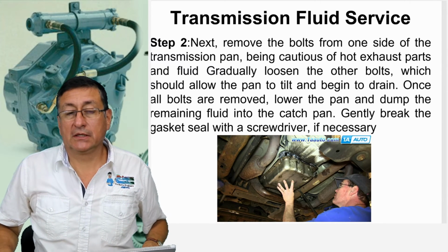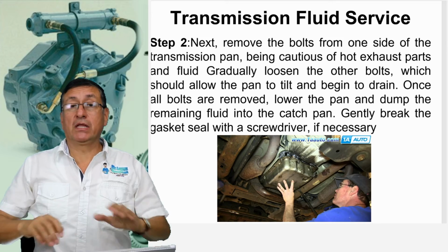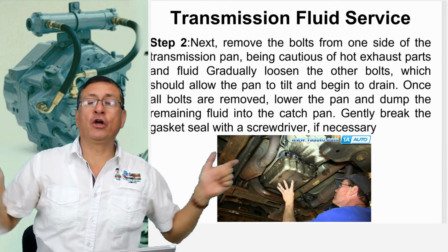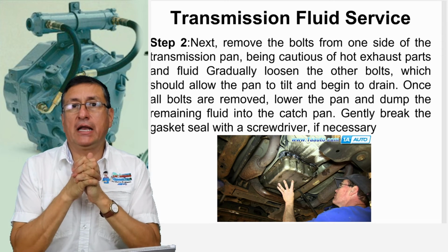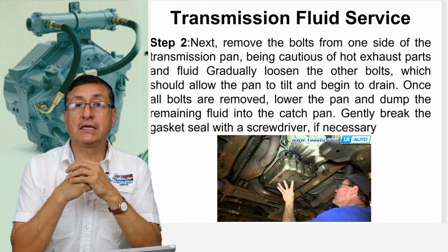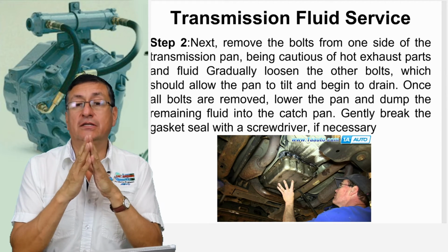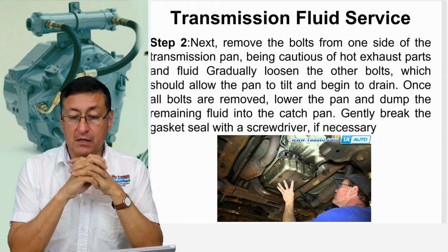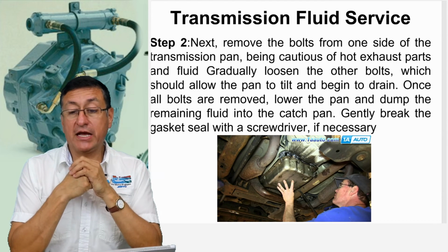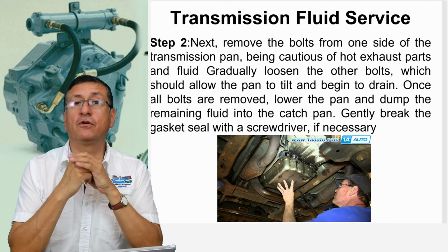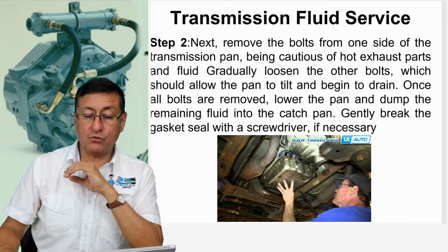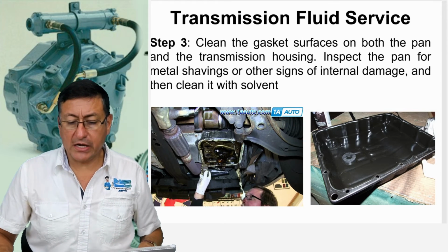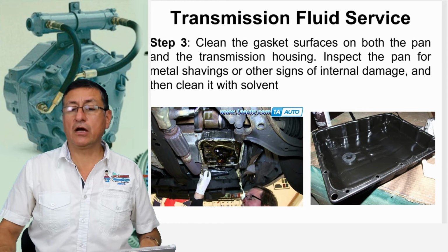Yes, you need to be prepared with gloves, with a lot of oil absorber pads around the area, and you need too much patience, too many rags, and you need to be organized and clean. Remove the bolts from one side of the transmission. Take care with the exhaust manifolds, because the exhaust manifolds normally are pretty close to the oil pan of the transmission. Okay, immediately you remove the oil pan.